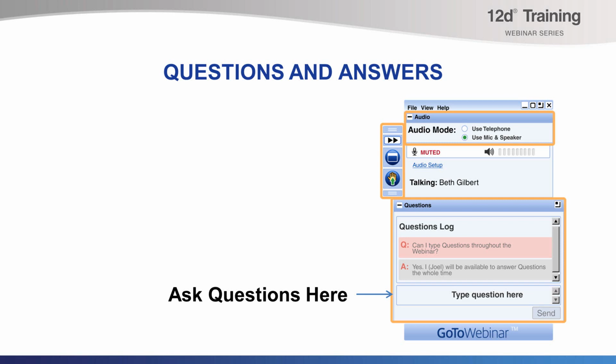Does the global close get affected if the survey reduction function is rerun? Yes, 100% it does. It's a CAD edit, and it will be replaced. So yeah, you will need to make sure that you lock your function beforehand, so that if you make any edits you won't lose that close. I think it would be a nice option in the future to be able to add in a global survey close into the data as well. So that's a good question. What's Stu's second one there, Lisa?